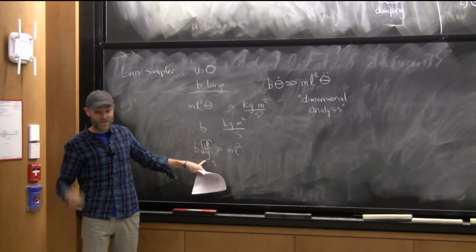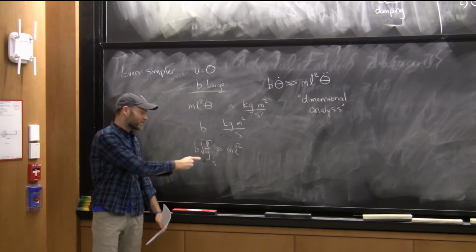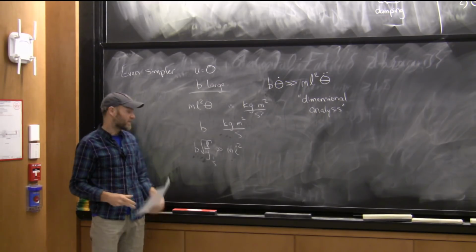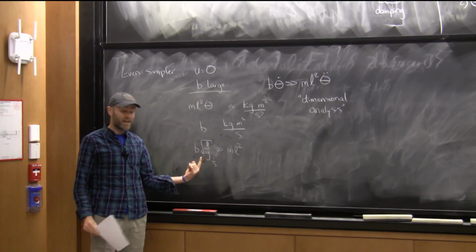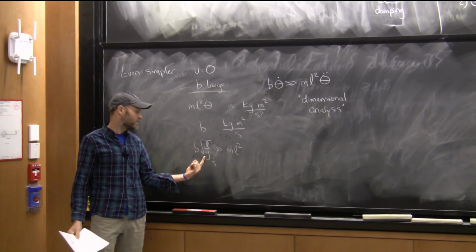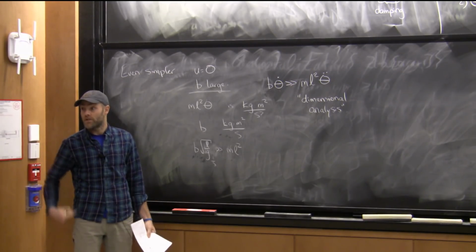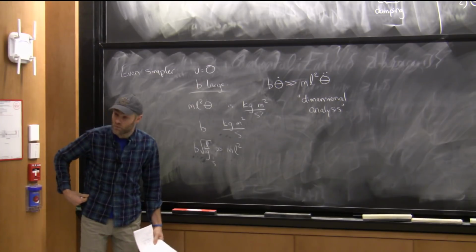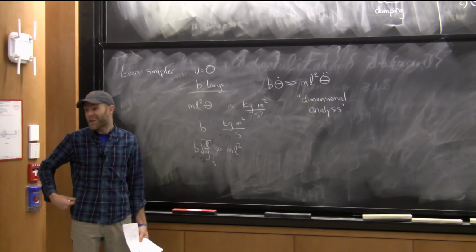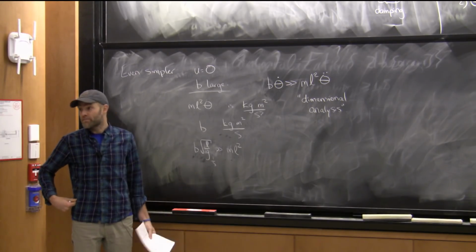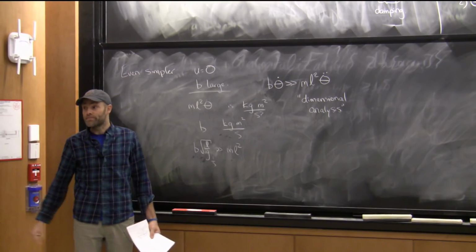But you'll see over and over in this literature, dynamicists being clever in picking out these characteristic time constants, or otherwise substituting in these variables. It turns out that this one's very relevant. Even for a humanoid robot, there are characteristic time constants that are basically the natural frequency of the pendulum. So it might be with my center of mass relative to my center of pressure, but actually the governing dynamics of walking are basically a pendulum. And you'll get some mileage even out of this simple one.